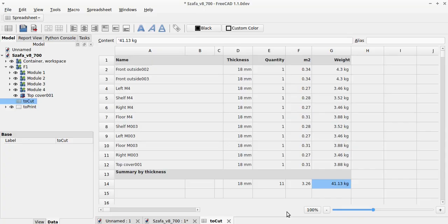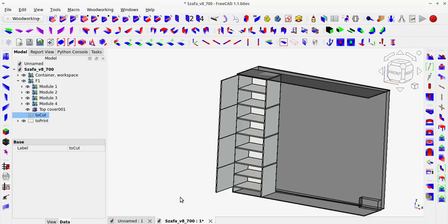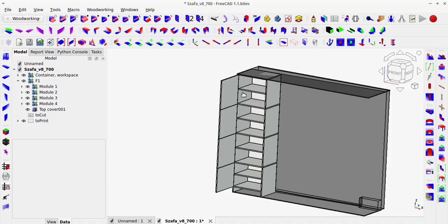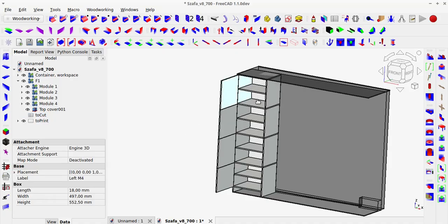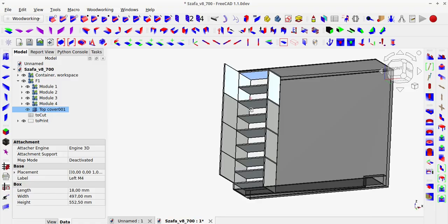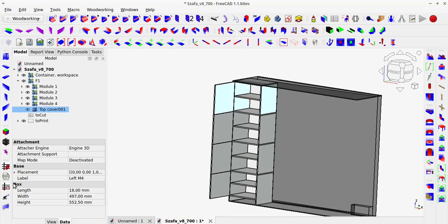I usually mount the modules on 8mm dowels to prevent them from slipping. However, in practice, such a module usually requires some support because the dowels not always fit perfectly into the holes, requiring a slight shift of the dowels or the side of the cabinet. So standing on a stool with such a heavy module may not be a good idea, as you could strain your back and then suffer from pain for 2 weeks.